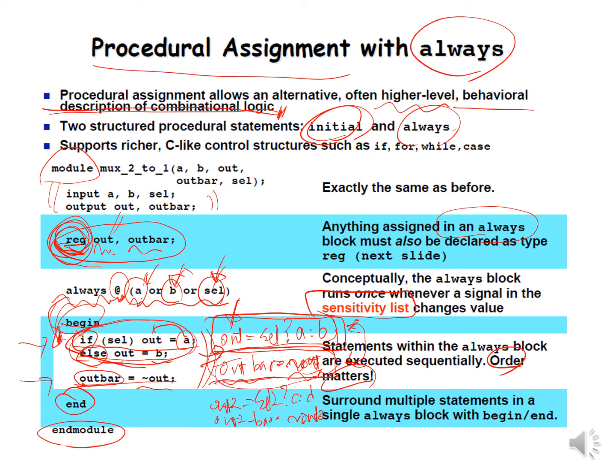To summarize, we have continuous assignment and procedural assignment. For continuous assignment, you use the assign statement, right? And for procedural assignment, you use the always statement. Okay.